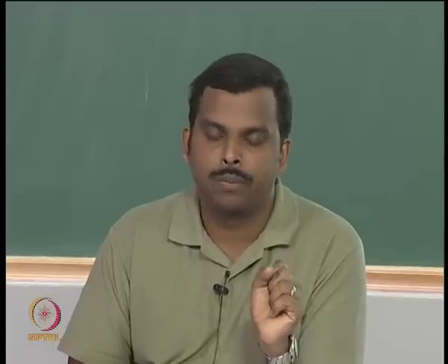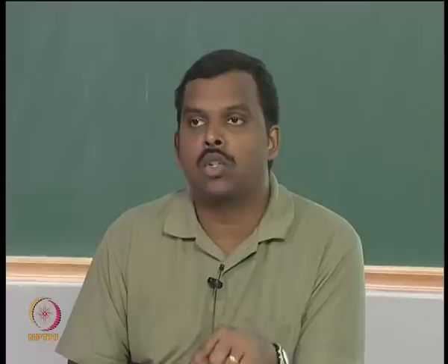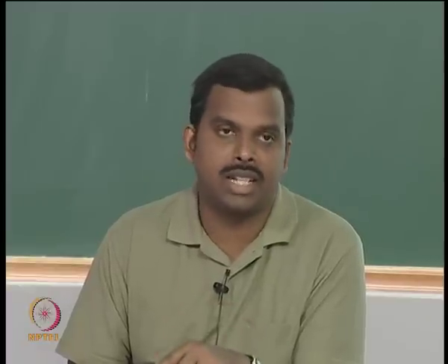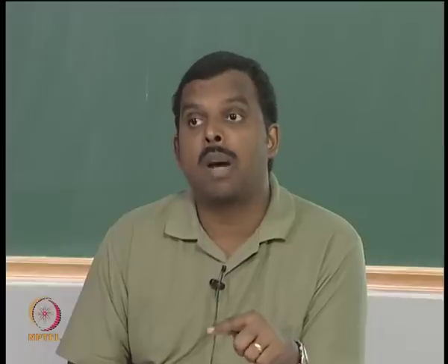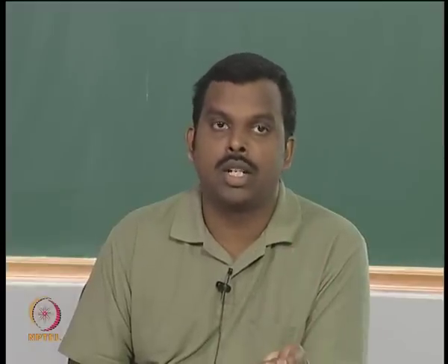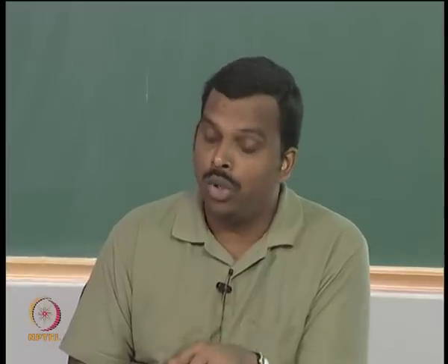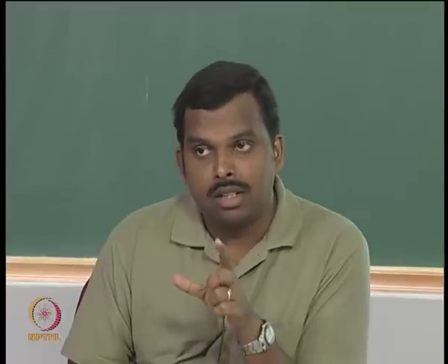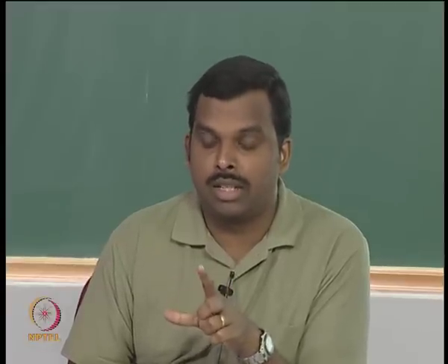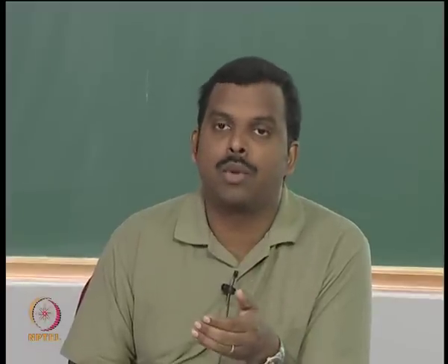Okay, so it's pretty good. So indirectly, what we are doing in this analysis is also trying to solve a design problem. If you can do this very nicely, then what should you be able to do? You should be able to come up with a convolutional encoder which will give you the best possible union bound estimate. Okay, how will you get the best possible union bound estimate? You have to maximize the distance between the two shortest vectors, and then what else should you try to do? You should try and minimize the number of closest neighbors.